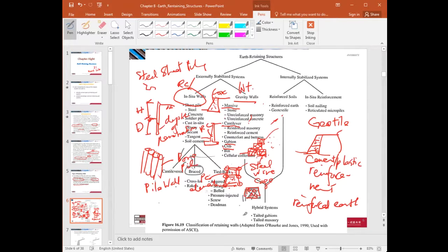You know what's braced? Braced means that if the retaining wall is too high, you have the sheet piling, and then you should use different levels of struts, right? Multi-layers of strutting, to arrest the tilting movement, the outward movement of the retaining wall. So that's the braced construction.